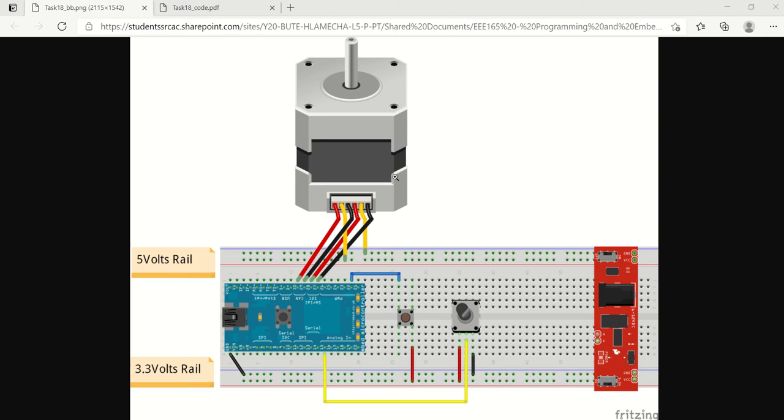So we have a similar setup for the motor. We should be able to wire that in okay. Just remember we need a 5-volt supply. And then along the bottom, what I'm wiring in here is a small push button and a potentiometer. So it's giving us an analog input in, okay? And I'm taking 3.3 volts down here at the bottom.